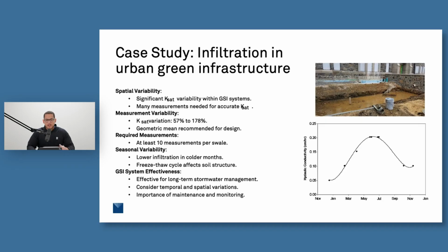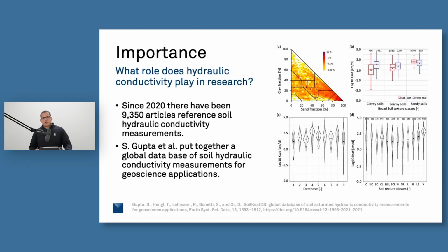Despite the variability in KSAT, they conclude that infiltration-based GSI systems are effective and reliable for long-term stormwater management when designed with consideration of temporal and spatial variations. They also conclude by recommending incorporating these variations into GSI designs and optimizing the number of field measurements for better accuracy. And of course, proper GSI maintenance and monitoring are crucial for sustaining performance over time.